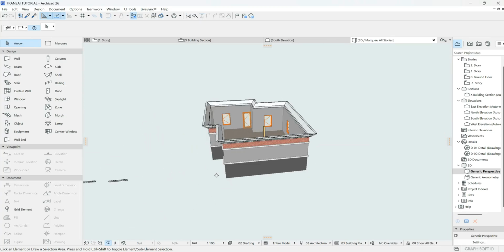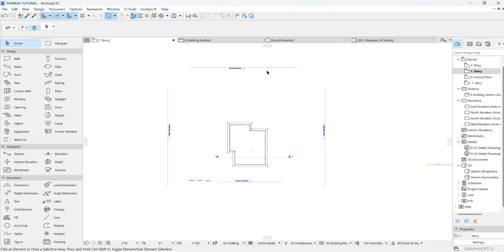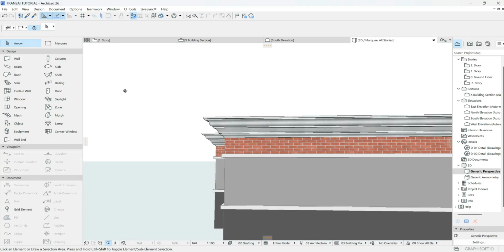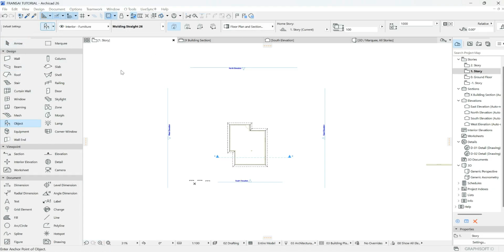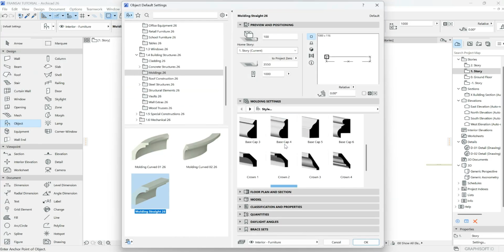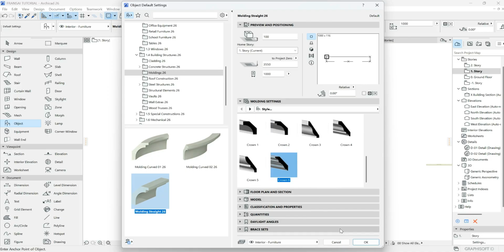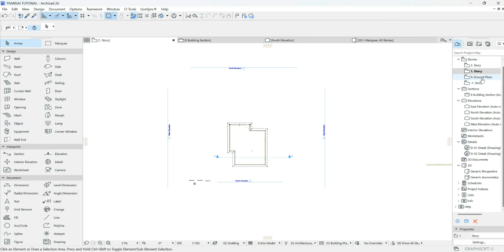So we've successfully placed our concrete fascia. Okay. So now we want to work with the one with straight, the ones without curves, just the one with straight ones. And Archicad does not have it. If we go there, we can see Archicad does not have it. But that is the one we want. Okay. What do we do? Okay, let's see. What we easily do is just use our complex profile.